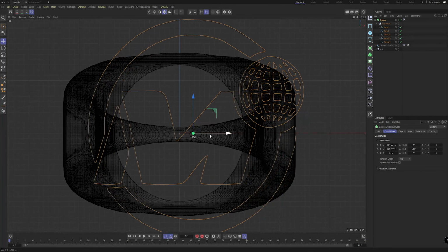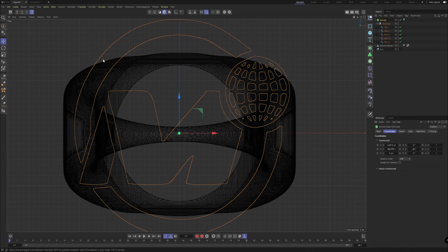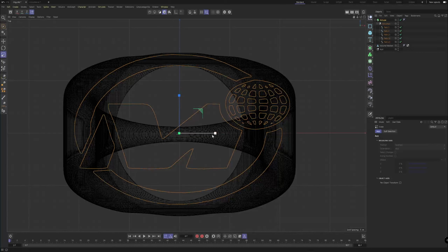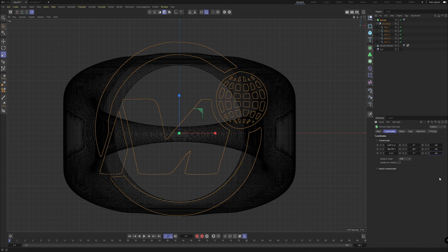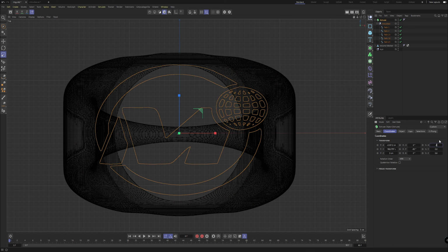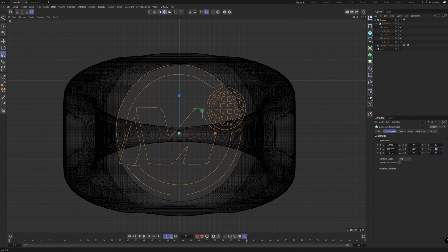So the one thing you can see about voxels and volume building is that the geometry is so crazily dense because we've been working with one voxel, and that is how it actually works. So you want to reduce that. I've been working on a project recently for university where I made all my models and a lot of stuff in Volume Builder, and it really bit me in the arse because you had to remesh it all at the end. So bear that in mind, because it doesn't always go to plan, but it is a pretty useful tool.